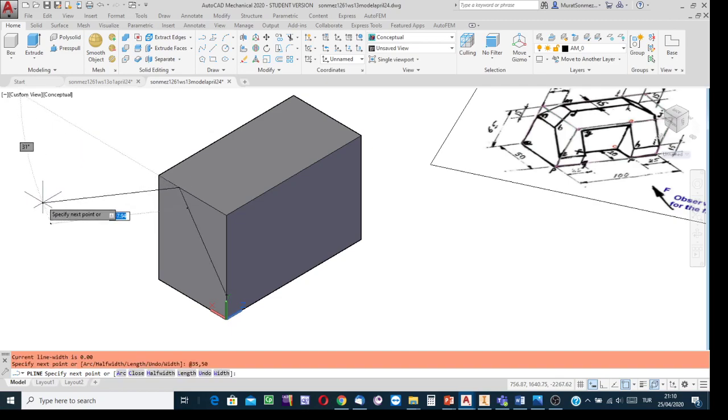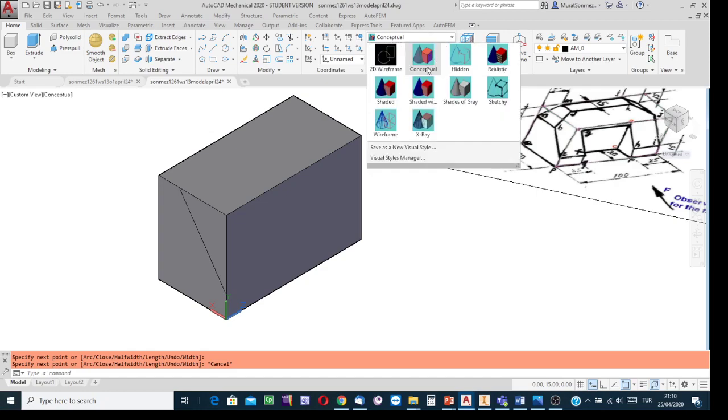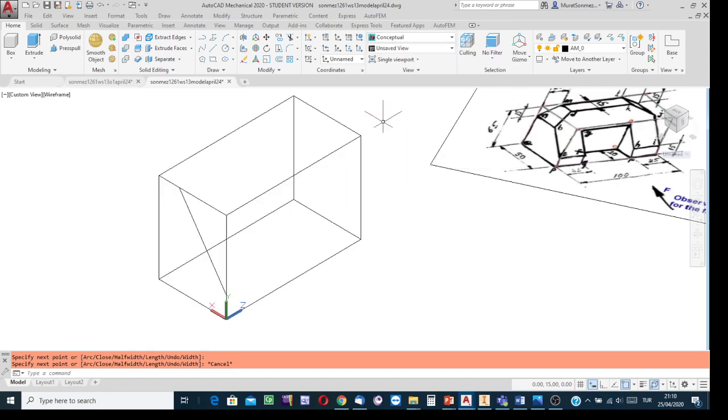Here is the inclined line. You see, I managed to create it. And then, to be able to have the closed profile, with the polyline process still in execution, snap this corner to have such a boundary, and then snap the starting point to have the other boundary. Press the escape button. And then if I change the visualization style, you can much more easily see what I have.